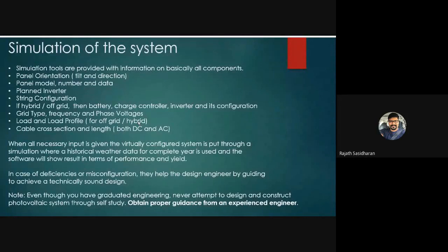And the beauty is that the simulation software can check whether your design is correct or not. In case you are exceeding the MPPT voltage, or the maximum input voltage, it can give you a heads up: no, you are doing something wrong. You need to change, or you need to reconsider the design. So these are some minimum inputs.